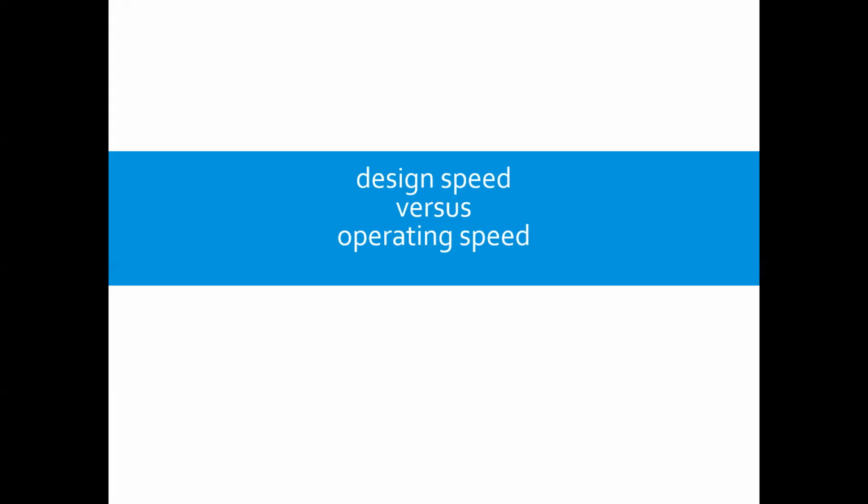The 15% of drivers who exceed this speed are generally aware of the increased risk they are taking, and they can expect to maintain a higher level of alertness, effectively reducing their reaction times. Desirably, the 85th percentile operating speed should be used for design.